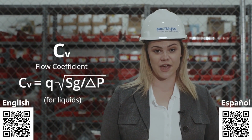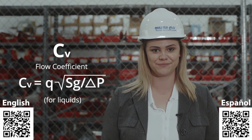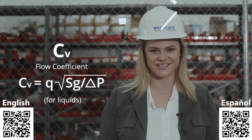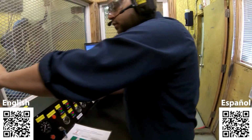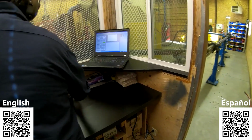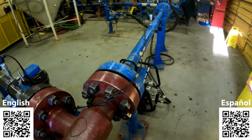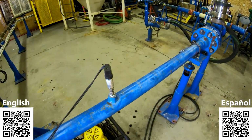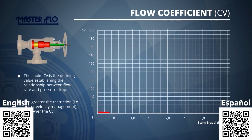To compare valve capacities and to size valves for specific applications, several coefficients are used. The first one is the flow coefficient. Flow capacity testing establishes a flow curve over the valve travel and provides a basis for comparing trim styles. Each valve type has a unique curve based on internal geometry. A greater restriction provides better velocity management but lowers the flow capacity.